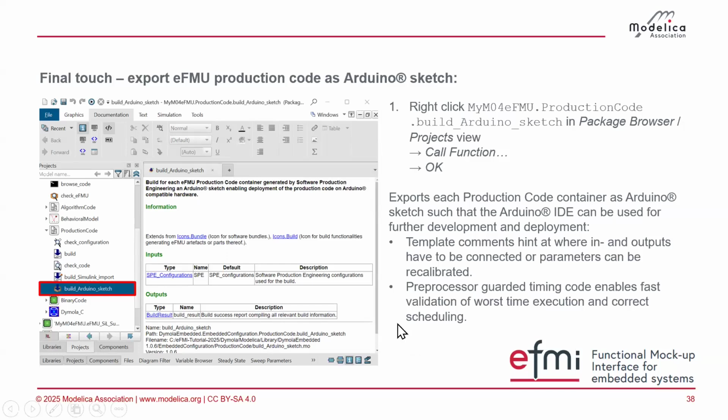And we will also generate code for the timing, because the Arduino, I don't know if you used it, is a rather simple device. It executes code as fast as possible. So if your sampling is every 10 milliseconds and the step happens to be finished after 2 milliseconds, Arduino will continue. So the virtual code runs much faster than real time. What you have to do is make it sleep in between and tell it, okay, now you can wait. And this code we will generate such that it really does the right real-time execution.